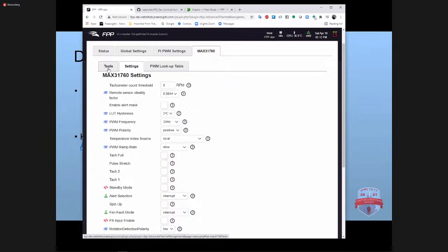If you have 1 or 2 fans, it'll ask you some questions and then set all those values for you. If you then want to go back and change them, you can, but without having to manually fiddle around with each one of these, the wizard will help put some of that standard stuff in place for safe values, depending on what kind of use case you have.